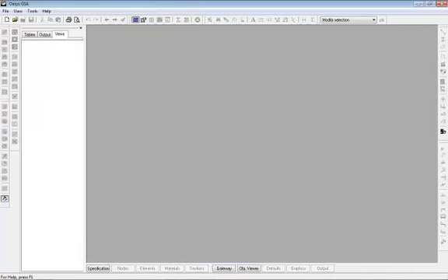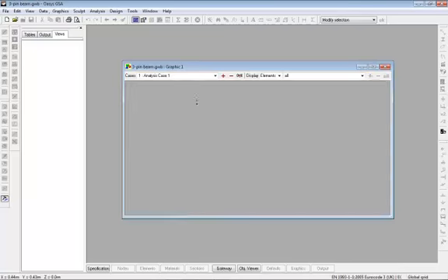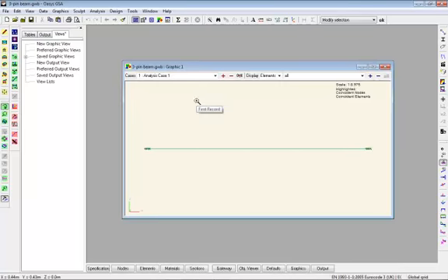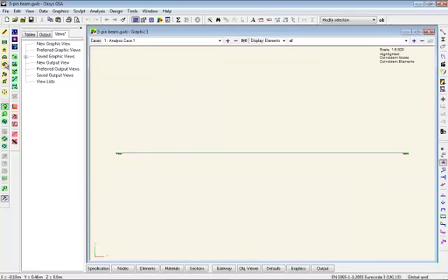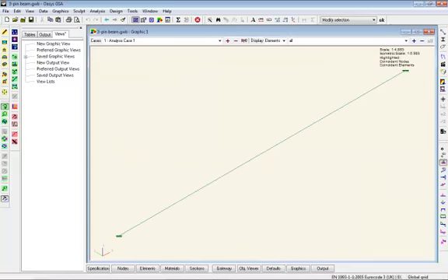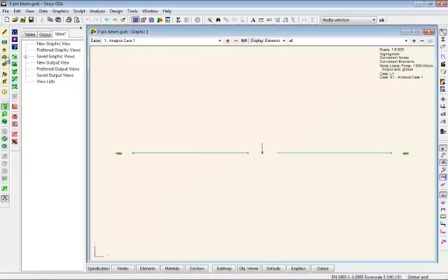Another example where we'd use non-linear is this example. If I look for an isometric, we have a point load in the middle of the beam, but this beam actually has, apart from the pins at the ends, also a pin in the middle. This is a 3-pin beam, and you'll remember from our first year structures lectures, this won't work under a linear analysis.